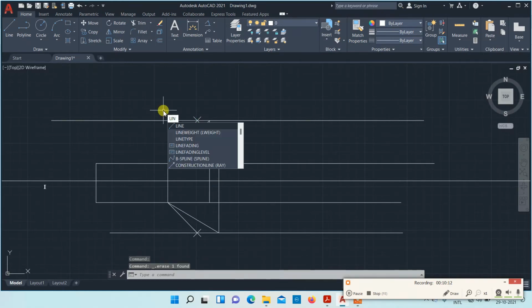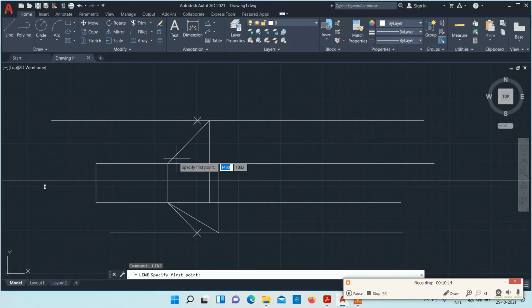Then draw a line by connecting these two points. Okay, so this is the projected length in front view. You can see that that line length is less than the true length. Okay, and you should check whether the answer is correct or not by checking whether these two endpoints of the projected length is along the straight line.